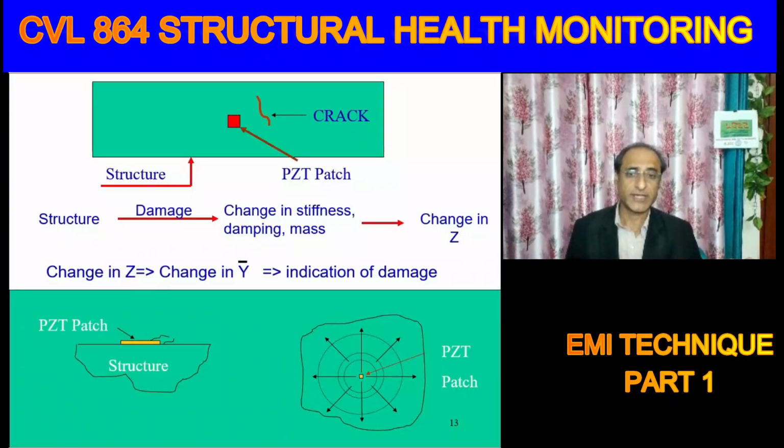Or in other words, we can interpret it from wave propagation: the patch is undergoing vibrations. So if it's on a surface, it's emitting waves readily away from it, and if there is any damage in terms of a crack, it will obstruct the path of the waves, and the waves are very small. Typically the order of the wavelength is a few mm.